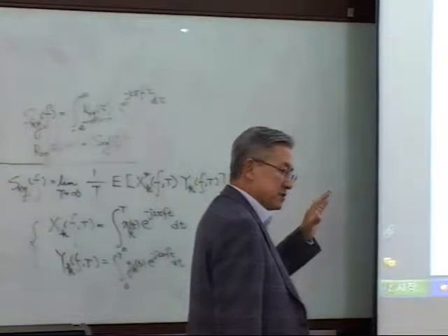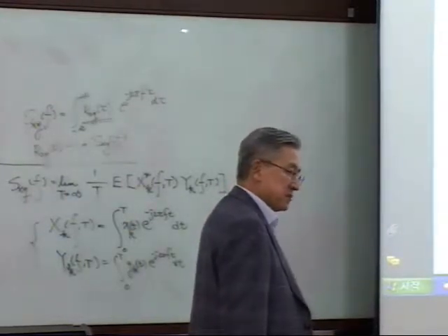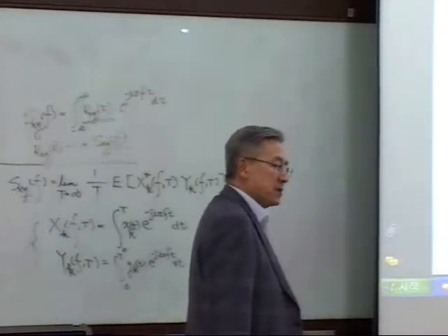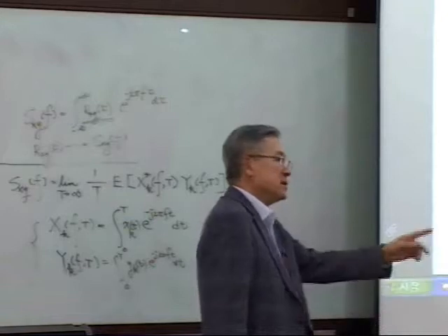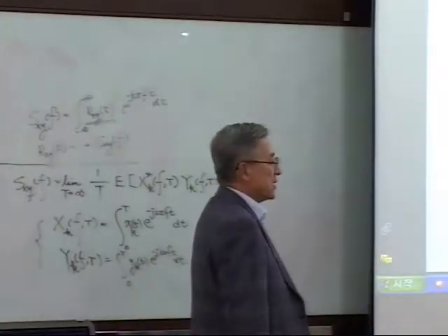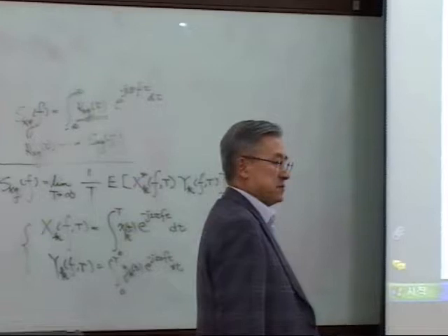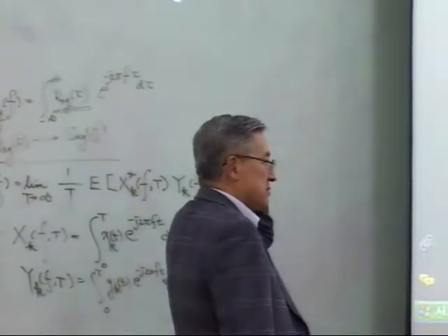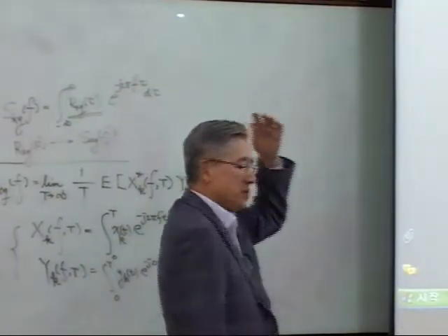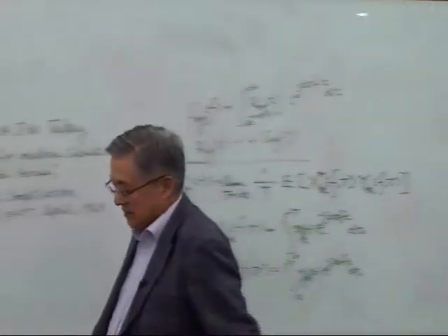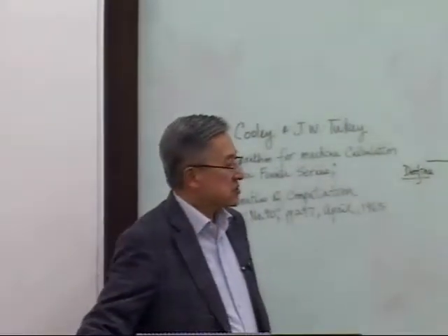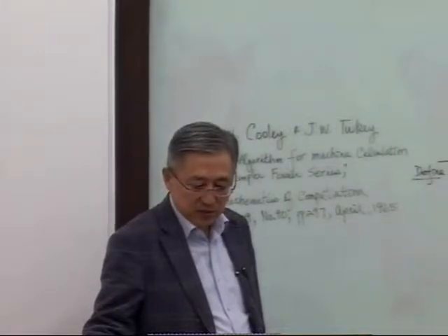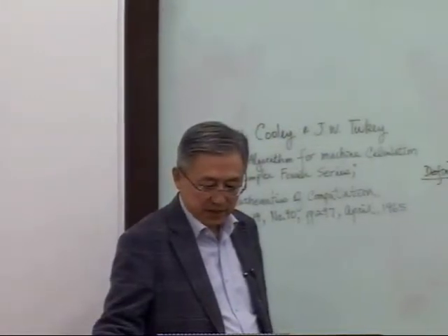When you say Fourier transform, this is really fast Fourier transform algorithm directly to go into frequency domain rather than computing the Rxy, then take a Fourier transform. Direct approach. So this is much faster. So this is the way the people use to get to the spectral function, whether Sxy or Sxx or Syy is all same.